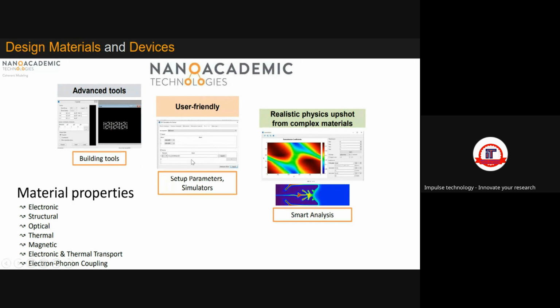So that you can set up your DFT parameter, DFPT parameter, NEGF parameter, like electron temperature, cutoff energy, exchange correlation function, K-point sampling, iteration control, Spintronics calculation. So once you define all the parameters, you can click on generate file so that this software will automatically generate your input file. So there is no need to write any script for any structure. Simply you can define the parameter and click on generate file.